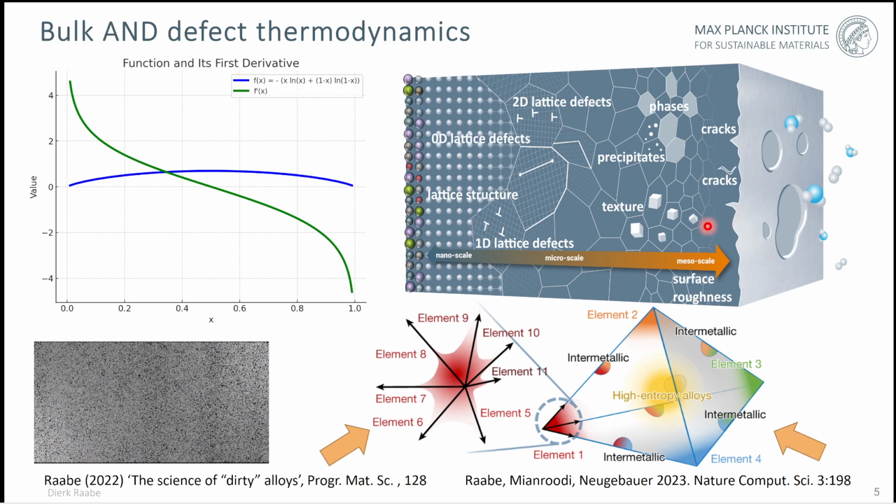We have cracked surface features, crystallographic textures, grain boundaries, heterointerfaces, precipitates, dislocations, substructures, and so on. That means all of these also attract specific elements and trap them, a feature called segregation to lattice defects. But this field becomes relatively complex and interesting and amenable to compositional tuning when we understand that in high entropy alloys, in massively mixed alloys, or in recycled materials with their many element types, the number of elements that are segregating to these defects becomes also very high.